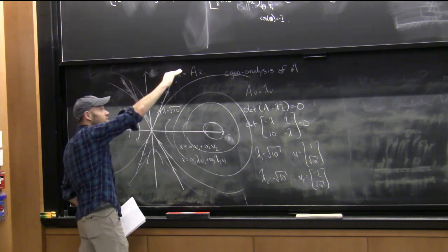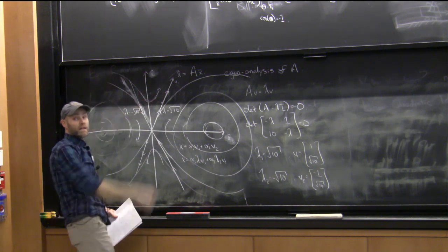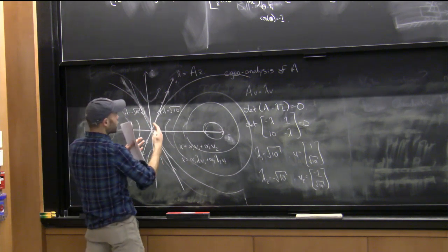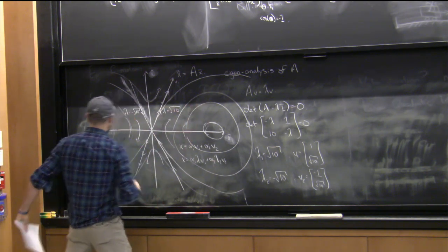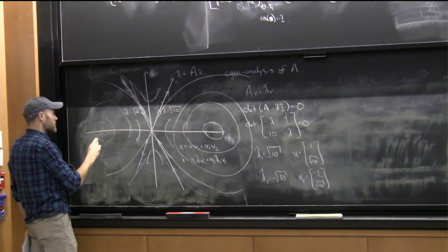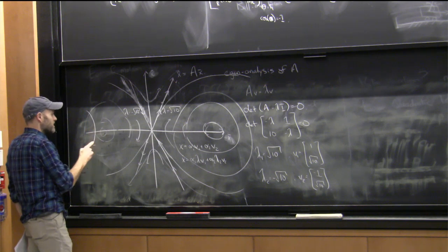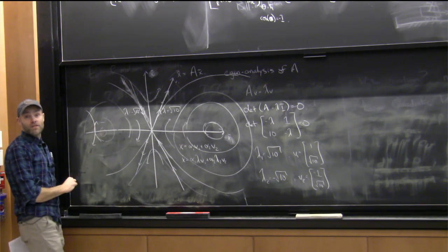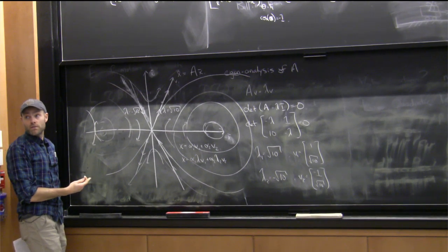And even this sort of, I missed the upright and I'm spinning around, even that gets captured pretty nicely, okay? Of course, if I go all the way past the eyeball, for instance, then the linear system's still going to say this, but the nonlinear system's saying this, so there's a limit to how well it's going to work.